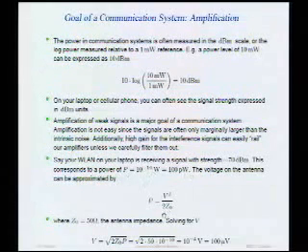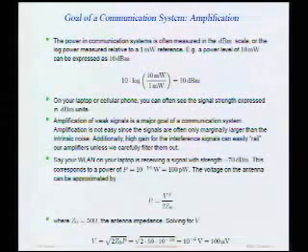We can translate that into an effective voltage at the input of the LNA, assuming the input impedance of the LNA is matched to your antenna with an impedance of Z0. Since power is proportional to voltage squared, that corresponds to approximately 100 microvolts. Now, that's a small signal, but it's not too bad. We can probably live with that. 0.1 millivolts.